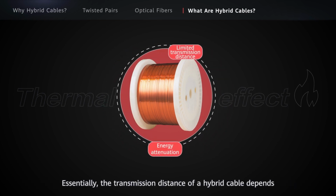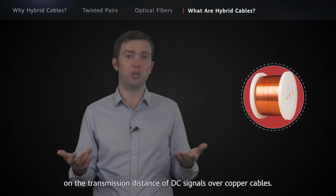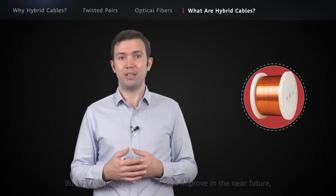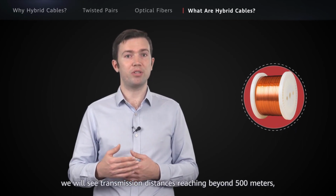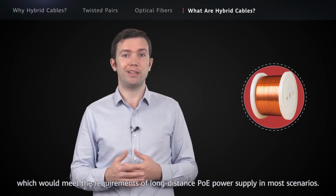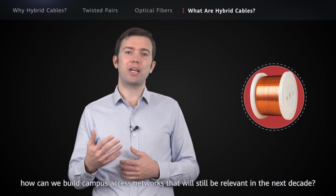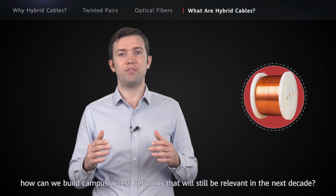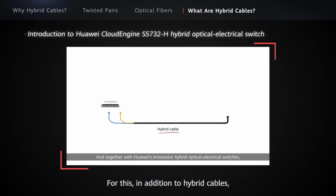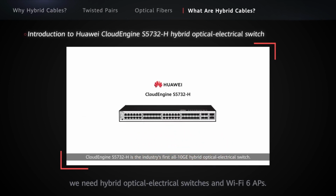Essentially, the transmission distance of a hybrid cable depends on the transmission distance of DC signals over copper cables. But as technologies and practices improve in the near future, we will see transmission distances reaching beyond 500 meters, which would meet the requirements of long-distance PoE power supply in most scenarios. With all this in mind, how can we build campus access networks that will still be relevant in the next decade? For this, in addition to hybrid cables, we need hybrid optical-electrical switches and Wi-Fi 6 APs.